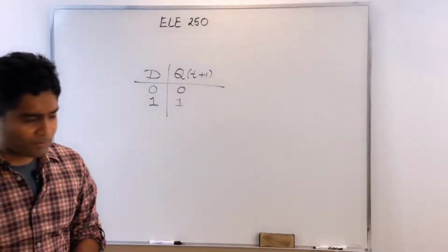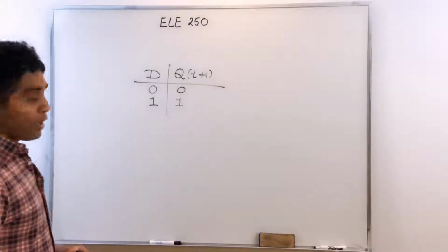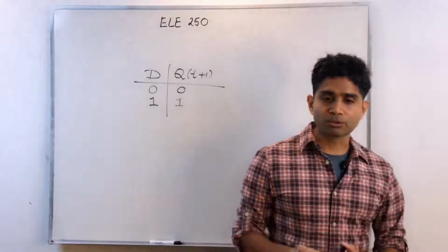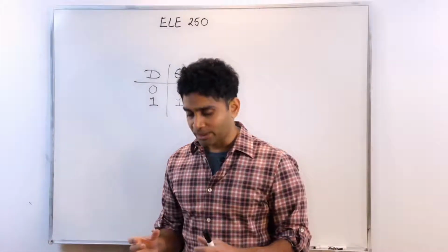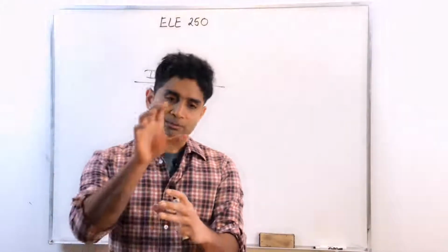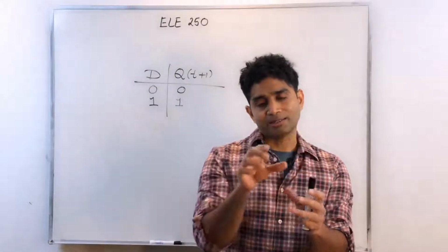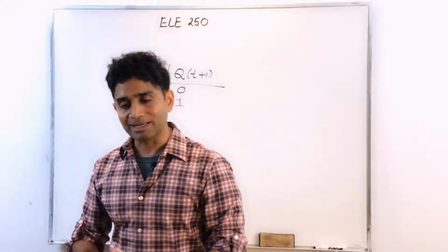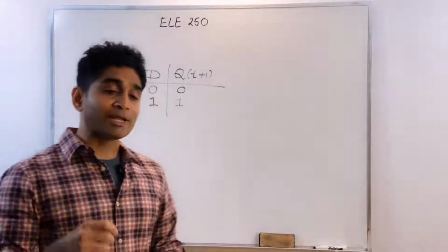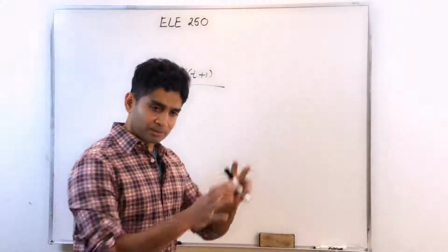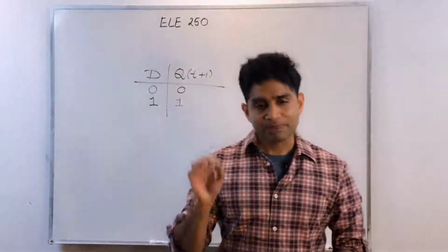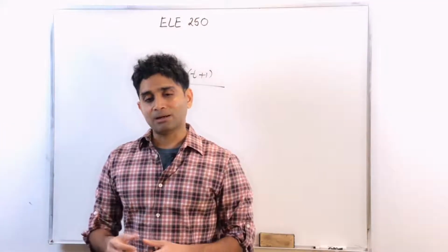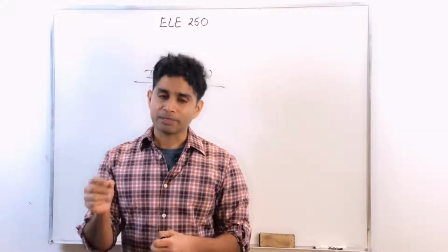So how would we obtain the memory state? We addressed this in the last class through the use of what is called the load enable input. In addition to a D flip-flop, we also use a multiplexer, and by using the multiplexer we can constitute a state called the memory state, with an additional load enable input to that entire system, so that I can place values on my flip-flop, which is part of a larger register, depending on what I apply on my load enable input.